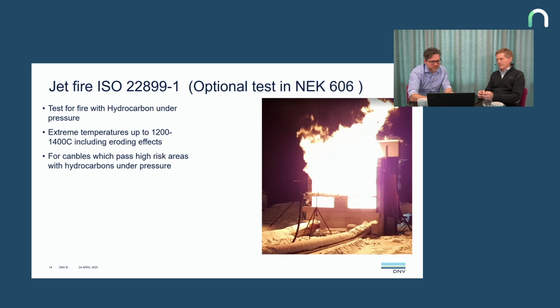Yes, and then we have the jet fire. This is a worst case. If you have hydrocarbons under pressure, and let's say you have a leak in the pressurized hydrocarbon oil tube or something, then cables may be exposed to this kind of fire.